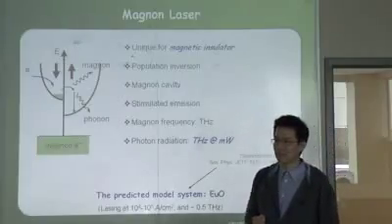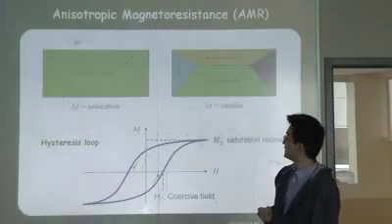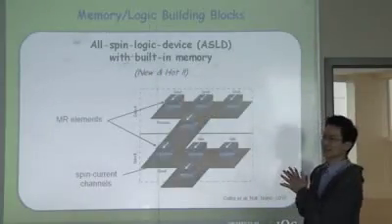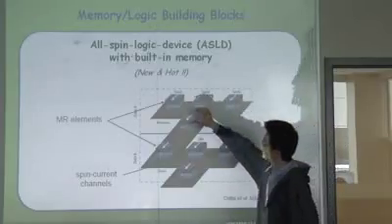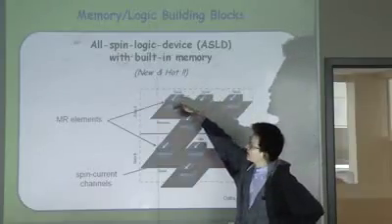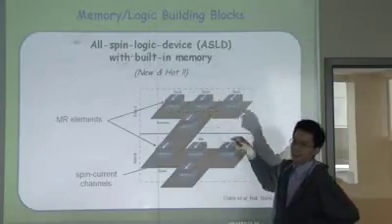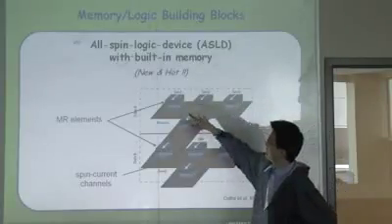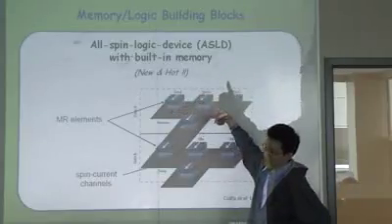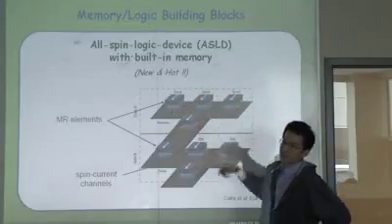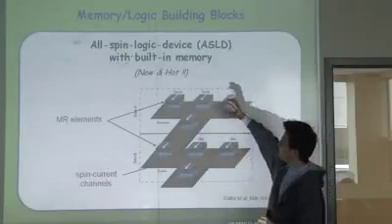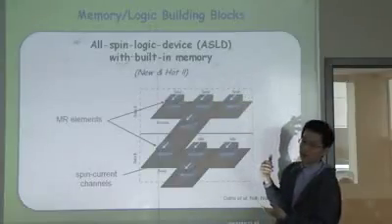On the next slide, or maybe 2 slides now, your all-spin device. Oh, okay. Yes. Can you just go over that again? I didn't quite understand that. Okay, so what happens is you see this complicated channeling combination. So each of them can send out a spin polarized current. This is based on spin transfer torque. And by combining them, for example, you can combine a spin up current and a down spin current. You can perform this AND and OR operation by combining these channels. And if you reverse the polarity, you can perform this NOT operation.